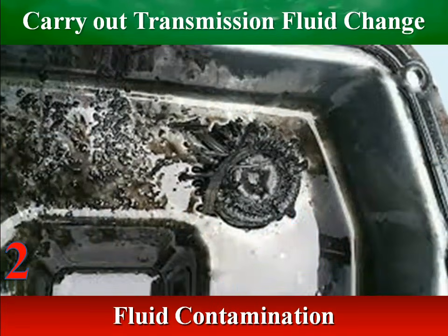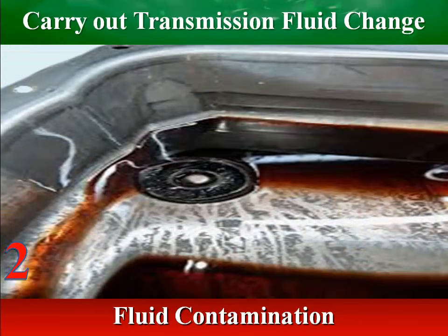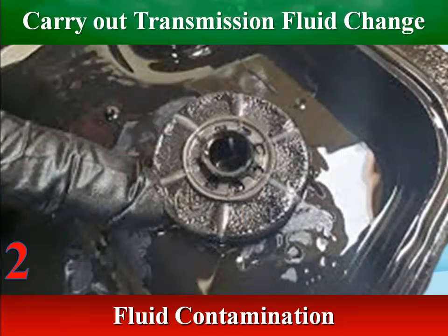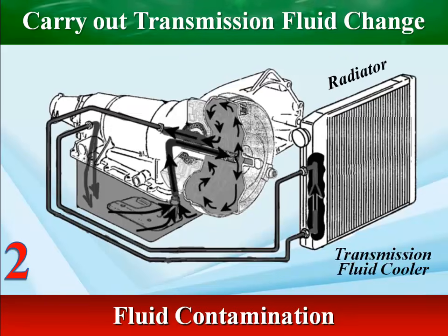At each fluid change, examine the fluid that is drained for evidence of dirt or engine coolant. A normal amount of condensation will emulsify in the fluid during operation of the transmission. However, if there is evidence of coolant, check the cooler, heat exchanger, for leakage between the cooler and fluid areas.